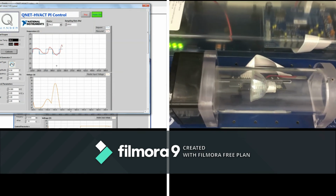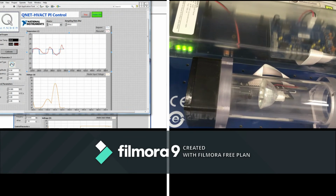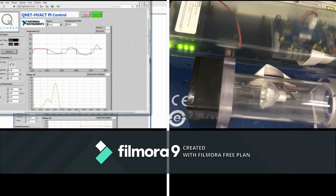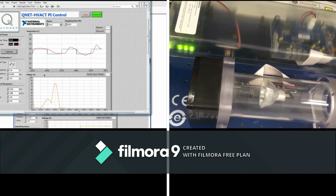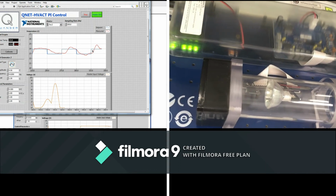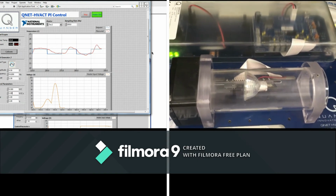So we can put this scale until 350 and we can stop. This is very obvious. The value of KI was 0.5, I think. Then we made it 1 in this cycle, then we made it 2 in this cycle, and we can see that the rise time is reduced, but overshoot is increased.